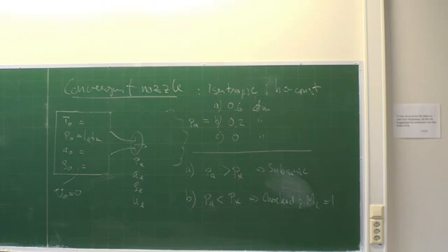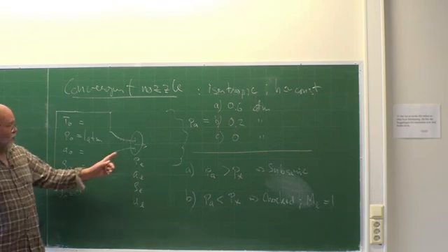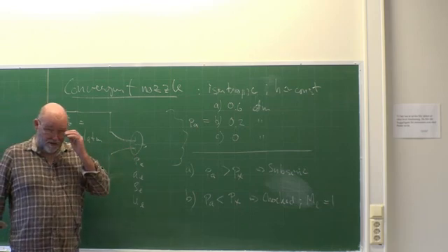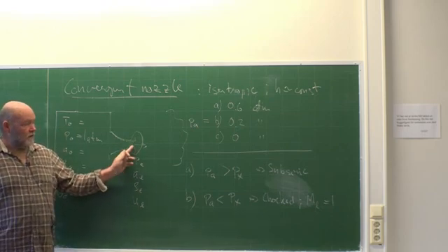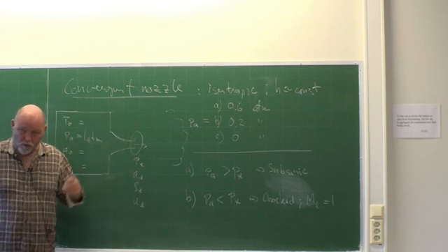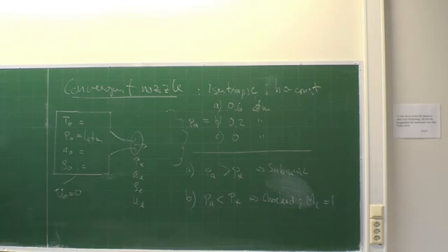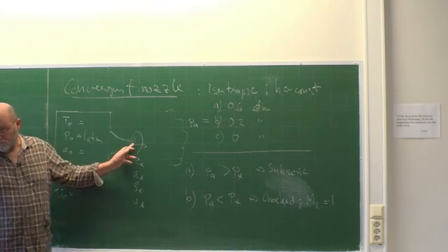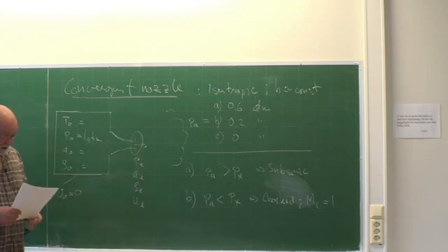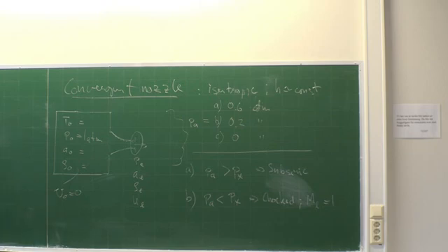And then from that one, you can calculate everything else. Yeah, you can find whatever you want here, speed of sound, density, velocity, whatever. Of course, you know from this area velocity relation, Mach 1 can only happen in the most narrow opening, when the area doesn't change anymore. So the speed of sound is then going to be equal to the velocity, since we have Mach 1 at that location. So no problem there.